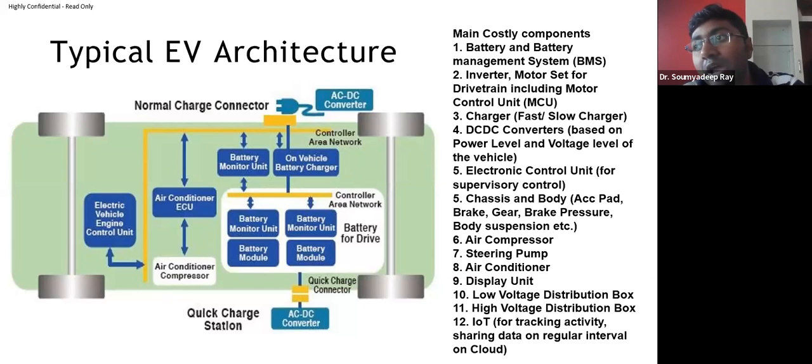As you have studied in electric drives, probably in 4th year, you need PWM switching, and you have to do the PWM switching optimally to ensure safety as well as the proper speed versus torque characteristics of the motor for your application. That control is done by the MCU, the motor controller unit.